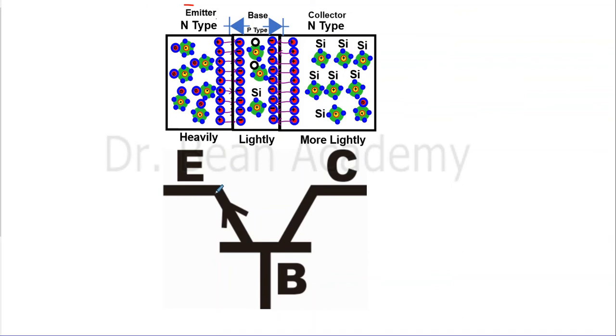So it will go from emitter to the base and then to the collector, and some current will of course flow to the base. It depends on the biasing conditions. So whenever I am talking, it should be according to the active mode or active region of the characteristics of the transistor. So in the active region, we know that the emitter and base junction will always be in forward bias mode, and base and collector will always be in reverse bias mode, because in other conditions it is either on or off, and we are not interested in that operation because there is nothing special in those operations.